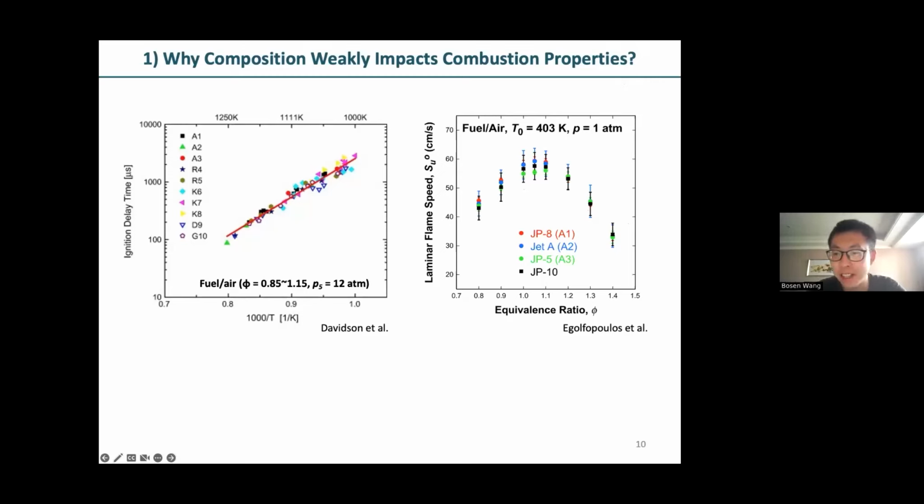As a developer of finite rate turbulent combustion models, the reduction by HyChem is very friendly, I think. But since HyChem is based on the assumption of timescale separation, as Professor Chen Zheng mentioned, and the chemical timescale difference of pyrolysis and oxidation is over 20 times, does it mean there are issues directly applying the HyChem mechanism to flamelet-like models? Explain why you have a problem in the flamelet model.